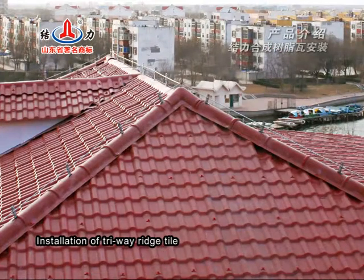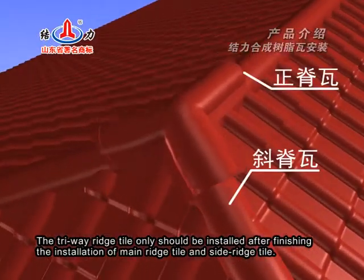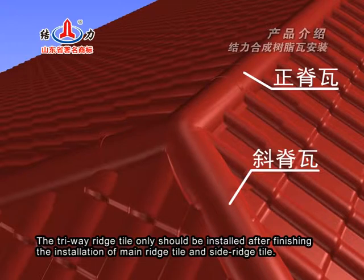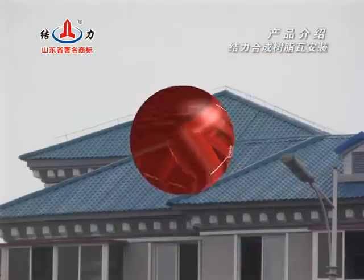Installation of tri-way ridge tile. The tri-way ridge tile should only be installed after finishing the installation of the main ridge tile and side ridge tile. The horizontal side should be on the top of the main ridge tile.